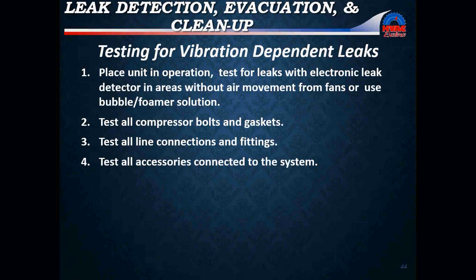So, testing for vibrations or a vibration-dependent leak. Again, put the unit in operation. Test for leaks with electronic leak detectors in areas without air movement from the fans, or use soap bubbles. Test all compressor bolts and gaskets. Test all line connections and fittings, and test all accessories connected to that system. Those accessories are going to be your filter dryers, your pressure controls, your sight glass, vibration eliminators, pressure regulating valves, so on and so forth.